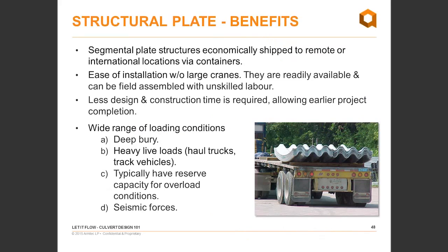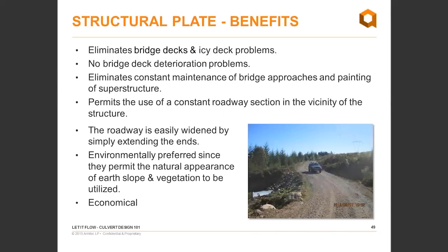And again, to sum up our structural plate, as you can see in the picture, it's a structure that's being shipped to the site, very economical, shipped to remote locations, with ease of installation without large cranes. You can use readily available machinery that's on site and assemble with unskilled labor. Less design and construction time required, allowing earlier project completion. And some of the benefits: deep bury applications, heavy live loads. They typically, when they're designed, have a reserve capacity and handle seismic forces.